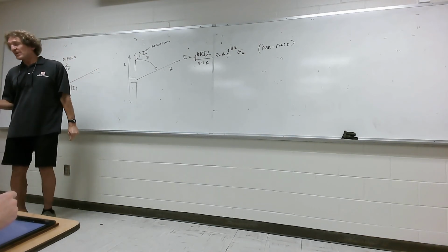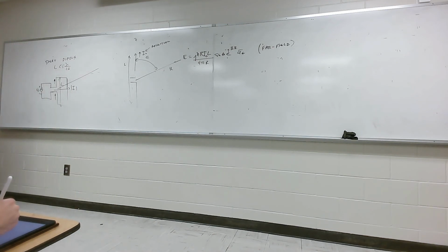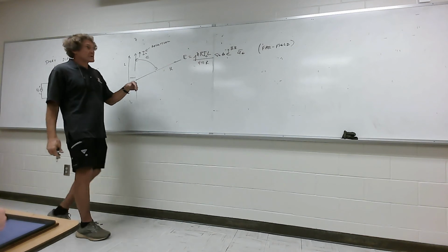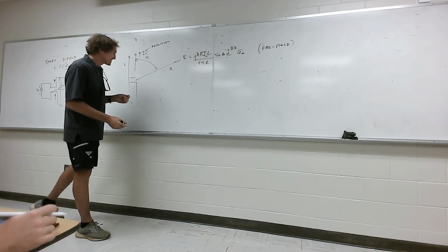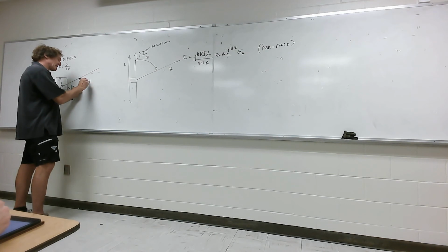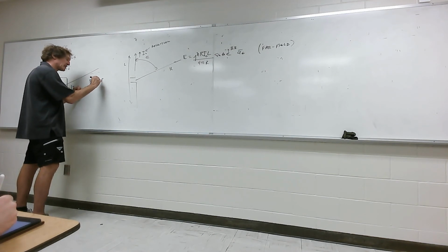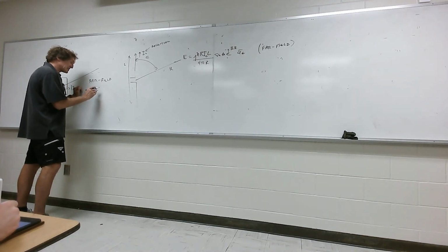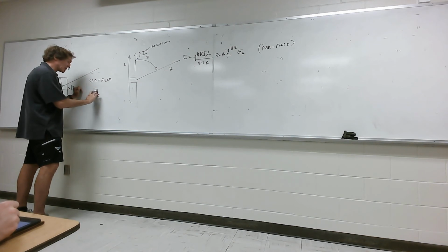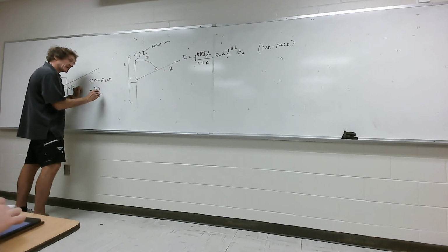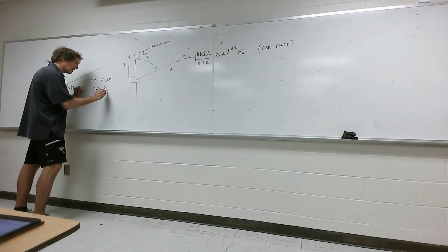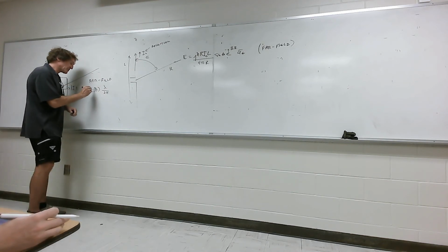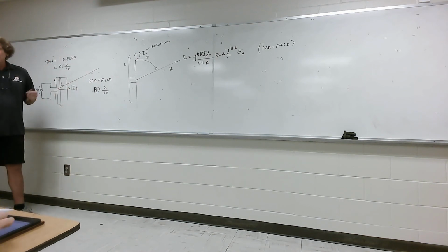And what do I mean by far field? Anybody want to take a guess? There's, quote, near fields and far fields. Far field is really where we're going to be at a position, and I'll tell you where the far field distance is. The far field distance is actually when the range R is greater than really lambda over 2 pi. And this is for straight wire antennas. It's not true for aperture antennas. So when I'm further than that away, I'm in the far field.